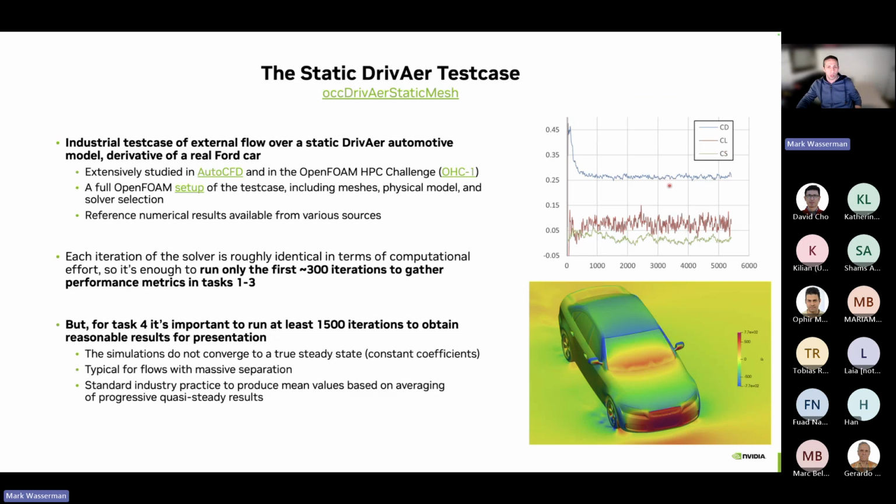And these coefficients were measured for this configuration and for this specific test case, both experimentally and numerically. And I do ask you to keep that in mind when you experiment with the solver settings and you find new and exciting features. Do a sanity check and test that the results that you obtain are reasonable in terms of their agreement with the experimental results.